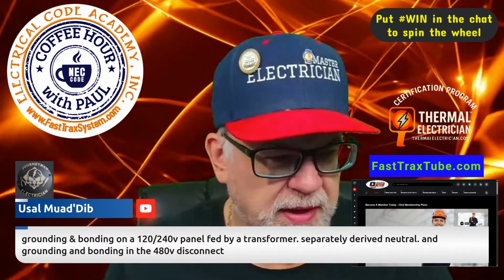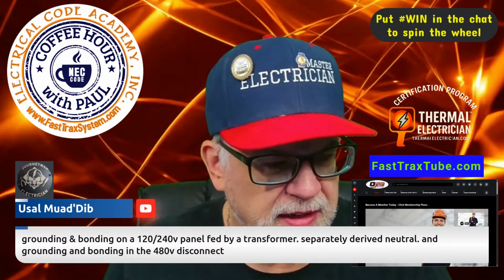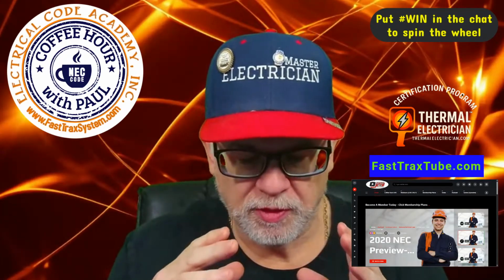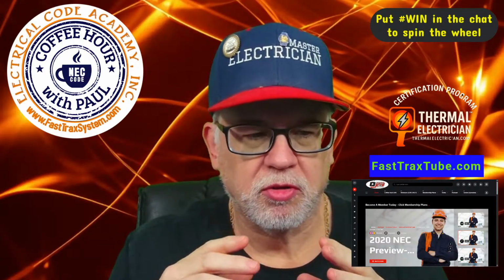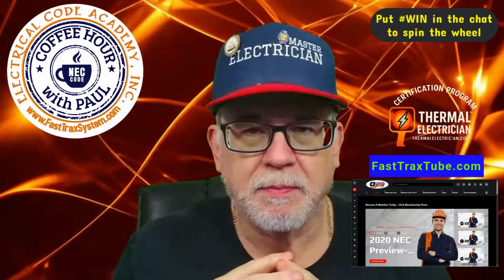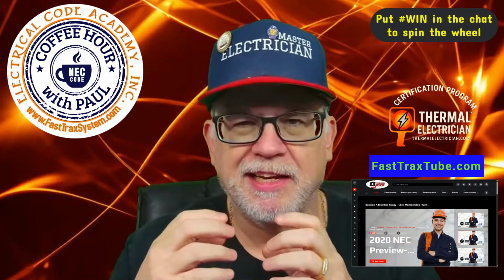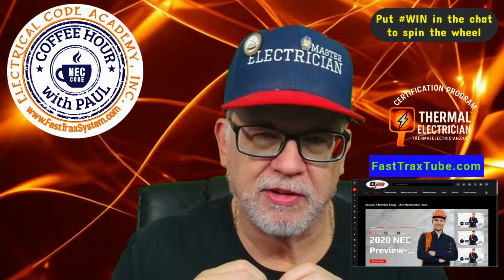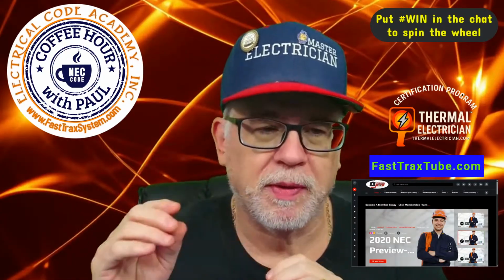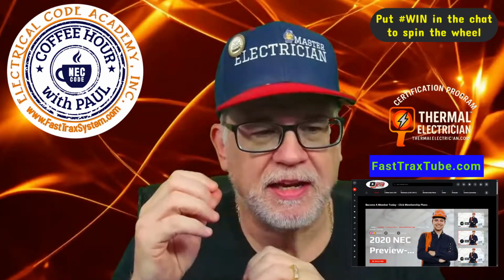You said grounding and bonding on a panel fed by a transformer, separately derived neutrals and grounding and bonding. It's a very broad question, as usual. So a transformer is a separately derived system. If you're talking from the secondary of the transformer to the panel, you're going to need what's called a supply side bonding jumper. You could bond it either in the transformer, where the case to neutral connection is called a system bonding jumper, or it can be done at the actual panel. Typically not both. So remember how you make these connections, but it depends on your setup.